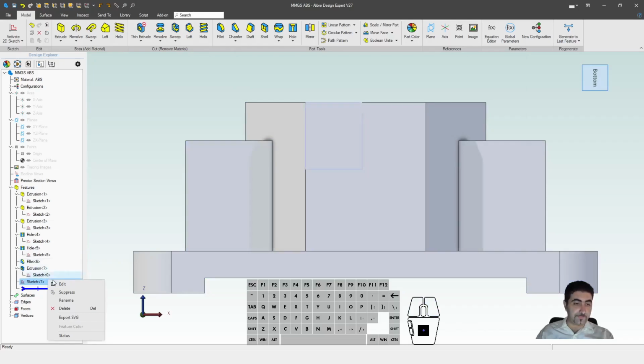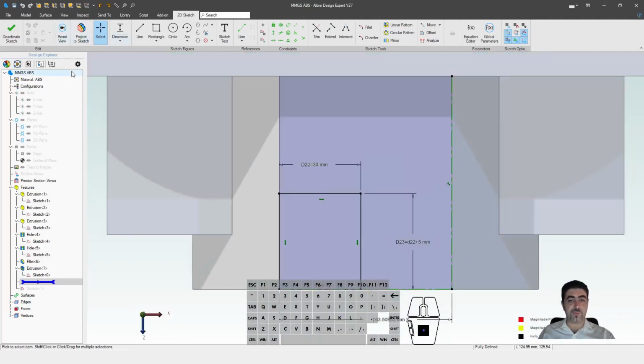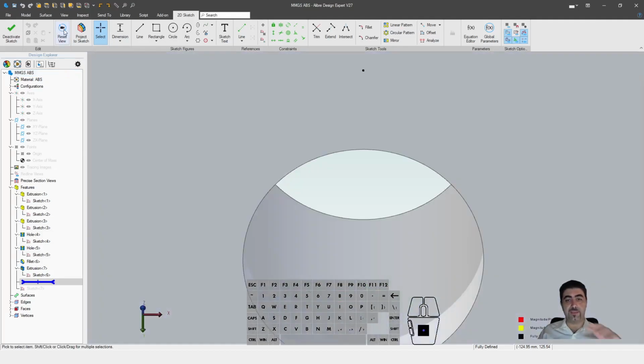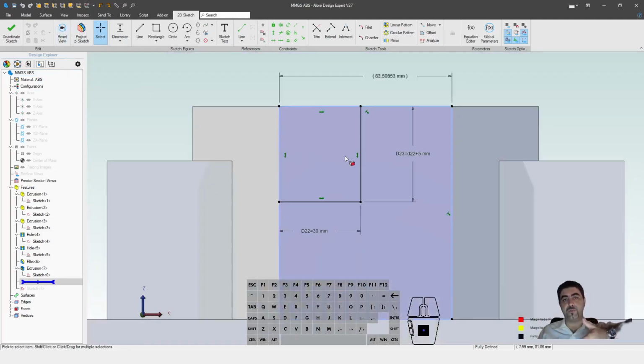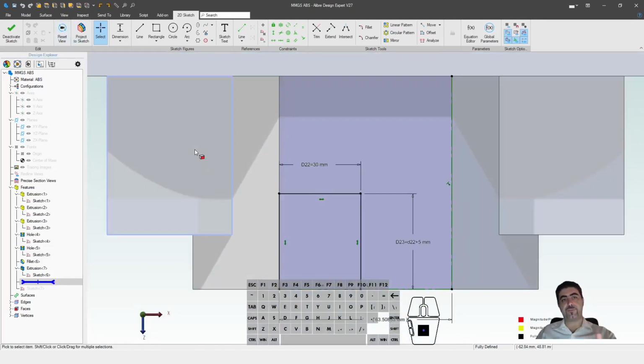Now, another thing that's come up, I don't know if it's affecting all of you, but if you hit the Sketch Reset view again, right, it gives you the opposite view from that plane. And when I asked for Alibre to give me the back view, the numbers in the equations, in the dimensions, got mirrored, right?